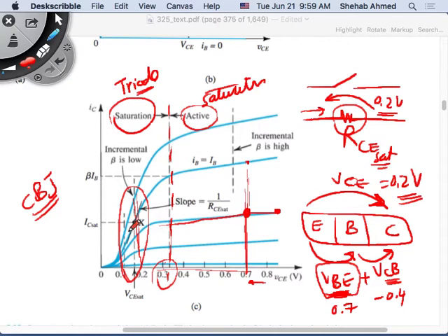It's interesting to put the device in saturation mode and triode mode because the voltage drop across the device is very small. So regardless of the current you're pushing through it, I still am maintaining VCE about 0.2 volts. So it's a nice device characteristic. But is this nice for low voltage switch applications? No. If I'm operating with 1 volt, 0.2 of that I'm seeing across the device.